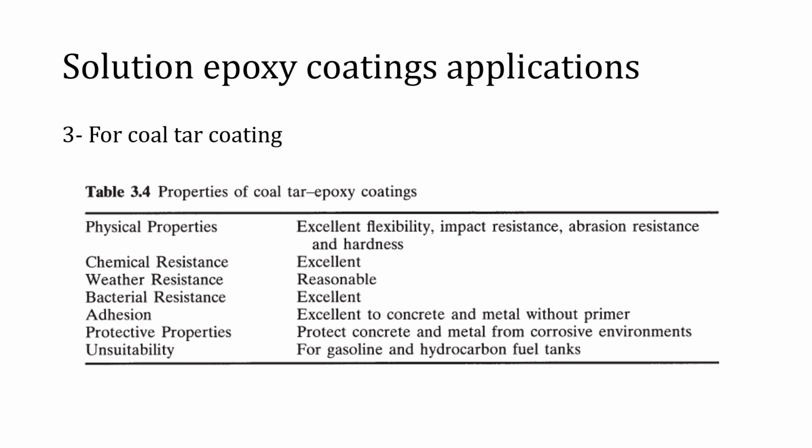These systems can be formulated as solvent-based coatings based on solid epoxy resins with EEW of around 500, solvent-based coatings prepared from liquid epoxy resins, as well as the more common type, high solids coatings prepared from liquid epoxy resins. In epoxy tar coatings, epoxy improves the thermal stability and water resistance of the coal tar, whereas coal tar improves the water resistance of the epoxy.